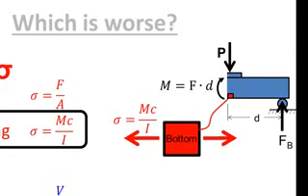So that moment is caused by the leverage of the reaction force at B, and we'd use that moment as the term M in this equation. And that, of course, is much worse than an F over A kind of equation, the force divided across an area. But in the Mc over I equation, M is actually a force at a leverage distance, so that is usually much worse.